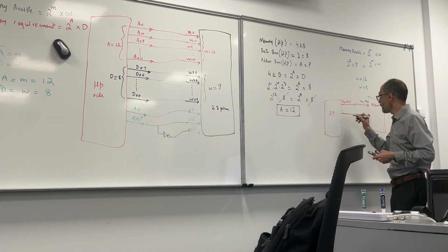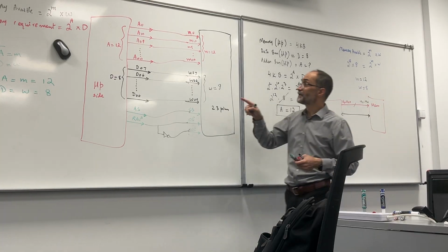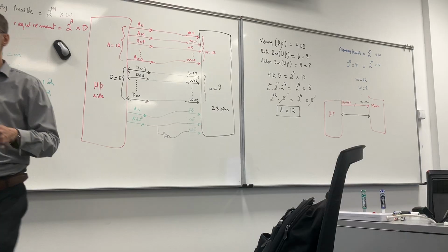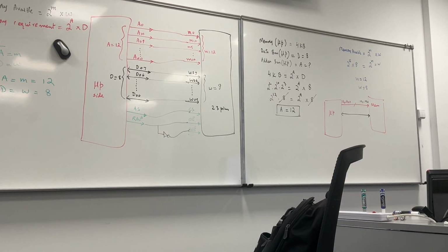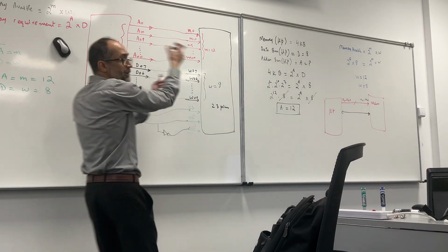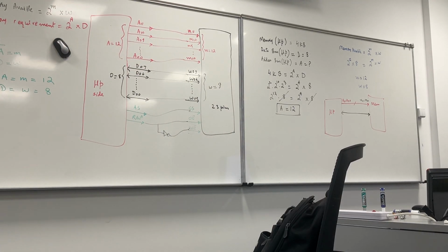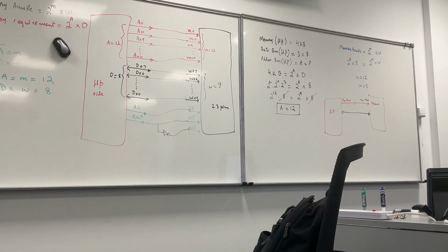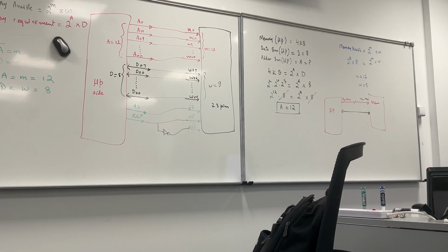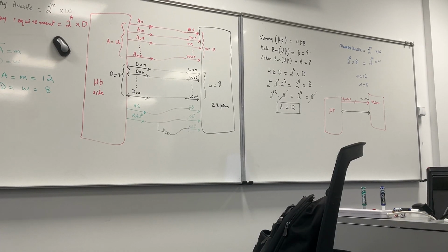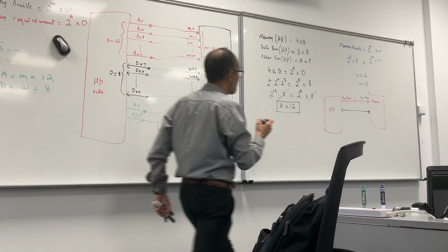What do we need to do here? Please remember, the address lines are unidirectional and the data lines are bidirectional, because we are either storing data into the memory or loading data from the memory. The direction of the data is from the microprocessor to the main memory for a store operation, and from the main memory to the microprocessor for a load operation. So it can be a read operation or a write operation. Clear?